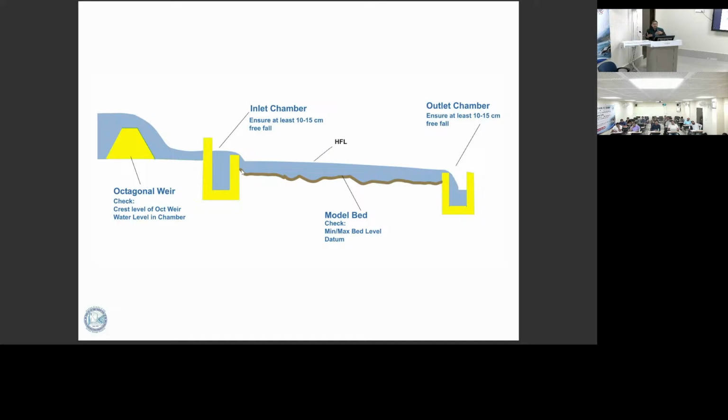What is discharge? Q is equal to A into V, that is the general formula, right? So A is equal to L into B, you know L into B. Then what is V? I told you earlier, V is equal to root of D. So L into D means length scale into depth scale into root of D, LD root D. This is the quantity. Suppose you have a geometrical scale of 100, then 100 into 100 into root of 100, what will this be? 1 lakh, I think, near about.